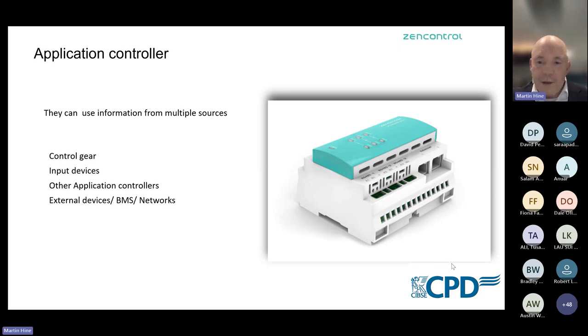In addition to that, you can use the sensors for absence detection, and there's increased information also from an environmental point of view in terms of some of the smart sensors that are available, which can also, within the same sensor, harvest temperature, humidity, noise, CO2 and various other elements over the DALI network.